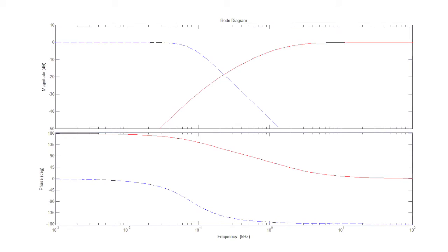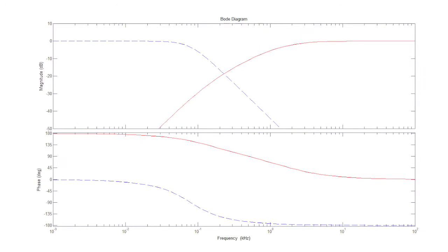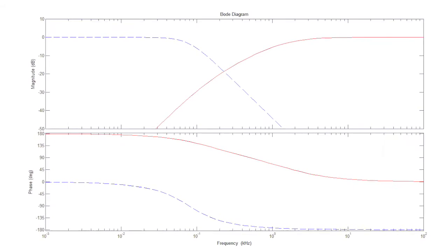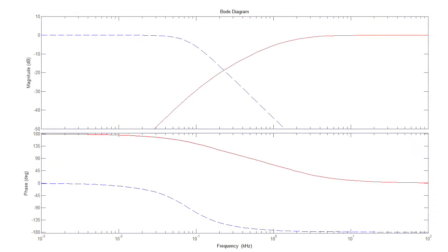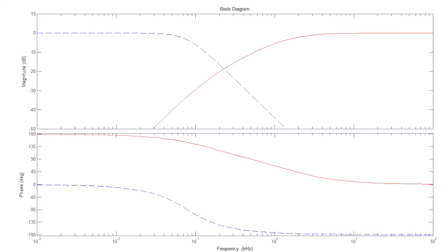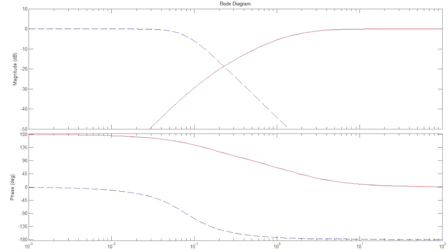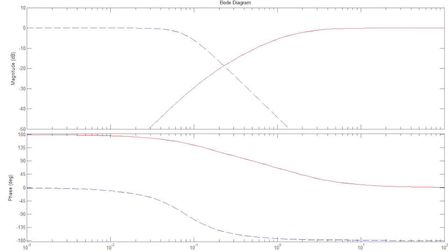These are the Bode plot simulations. From these, we were able to calculate transfer functions for both the high and low pass filters. Using these transfer functions, we were able to calculate the cutoff points of the low and high pass filters and scaled the low pass to 80 Hz and the high pass to 1500 Hz.